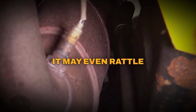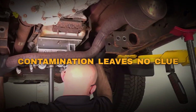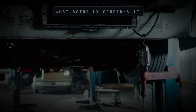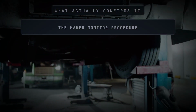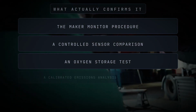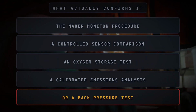A physically damaged converter may rattle because the internal material is broken. A converter damaged by a severe misfire may contain a melted substrate. A contaminated converter may lose efficiency without creating an obvious restriction. Professional confirmation depends on the vehicle and the equipment available. It may include the manufacturer's catalyst monitor procedure, a controlled comparison of upstream and downstream sensor behavior, an oxygen storage test, a calibrated emissions analysis, or a back pressure test when restriction symptoms are present.